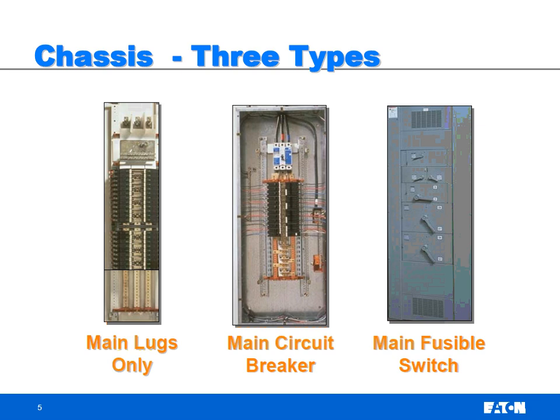The other thing to consider, which is often the driver, is the convenience of disconnecting the panel. Often you'll see it this way. If I feed up one floor, my switchboard's here, I'm feeding my panel board up one floor, and I'm an electrician up there, and I need to shut that panel off to add a breaker or work on it for some reason, then putting a main breaker up there is going to add the extra benefit that while I'm at the breaker, I can turn things on and off rather than have to come back down here and go back up.